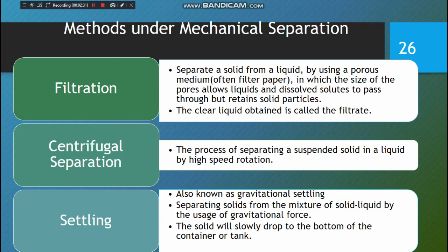In turn, it will build up the cloth as a porous cake. So, the other definition of filtration is that the solid particles in a liquid or gas are removed by passing the mixture through a porous medium, which retains the particles and passes the liquid. As a summary, filtration is used to separate a solid from a liquid or a solid from gas.